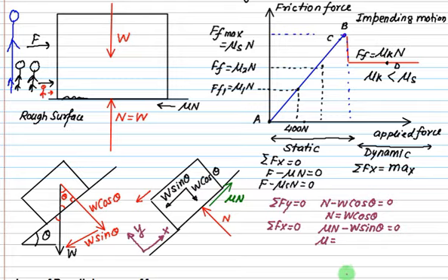From this we can define the angle of repose. Do you remember the angle of repose? Self-locking concept. So suppose this angle is theta, and suppose phi is equal to tan inverse of mu, and suppose theta is equal to phi, so the body is in what? On the verge of motion.